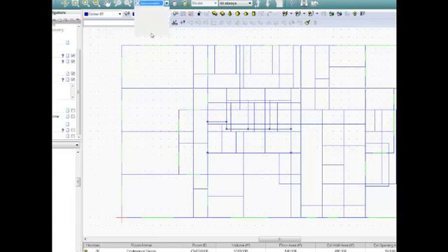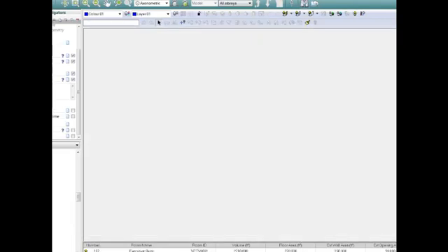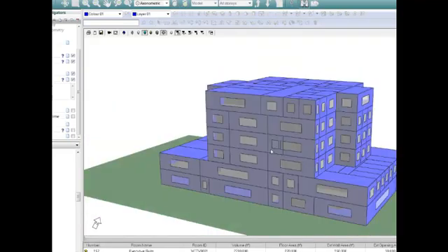So I'm just going to go to an axonometric view. And you can see that there's some glazing on the model. I'm just going to open the three-dimensional view of this. You can see that the percentage glazing that we have applied to our model has been set on the center of the exterior walls. So this is a very quick way in Affinity and with IES to say, let me test 25% glazing, 30% glazing. Again, it's all about that quick iterative design when we're working at the early stages, and even when the design is developing. So I'm just going to close out this three-dimensional view.